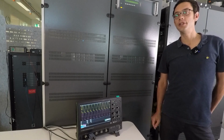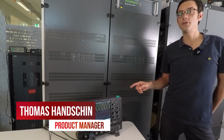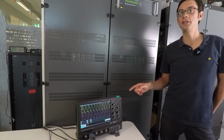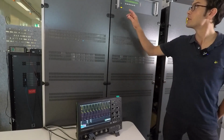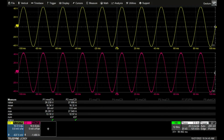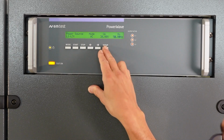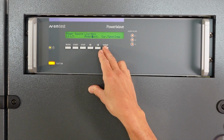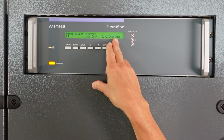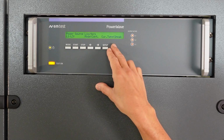I showed you how to use the RMS current limiter in AC mode. Now I'm going to show you how to use the peak limiter and the effect of the peak limiter in RMS. So I'm still at AC mode, 30 volt, 50 Hertz. I'm going to go to the settings, so an AC 30 volt. And this time I'm going to still use continuous, but I'm going to change the type of the limiter from RMS to peak limiter.